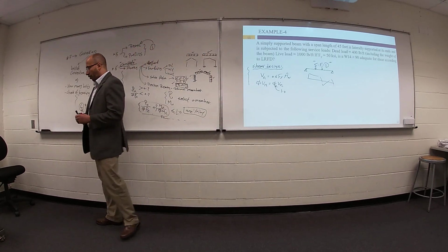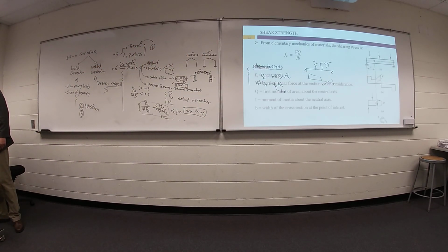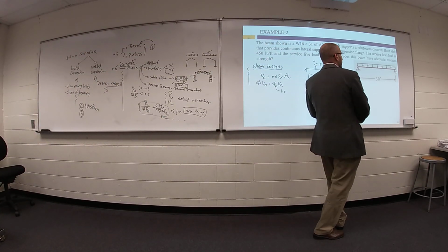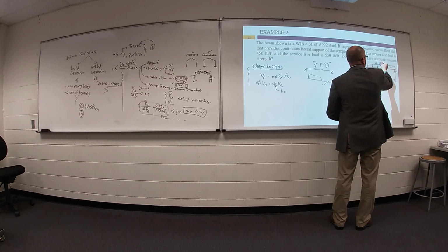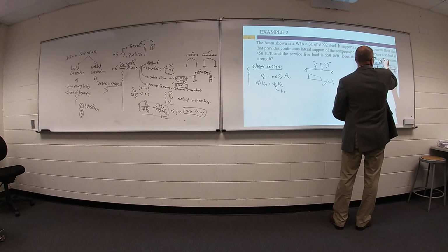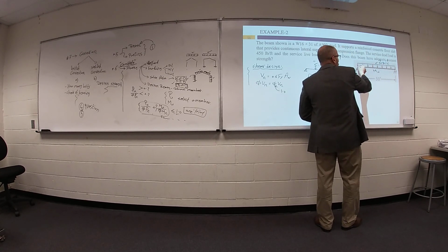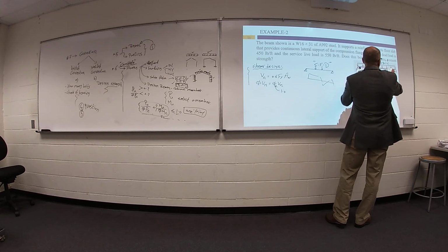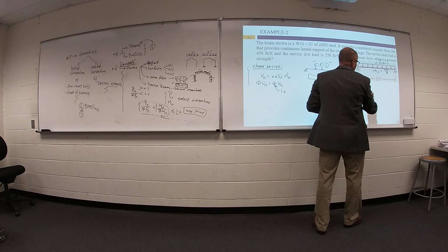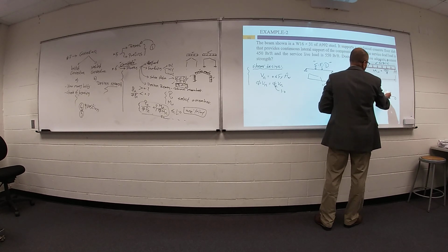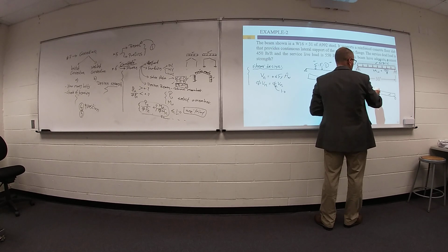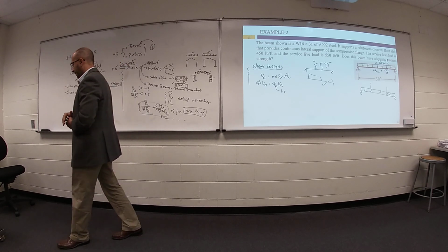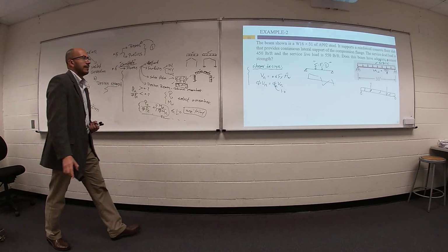Also, for the previous problems, if you have trouble determining M ultimate due to the given dead load and live load, after multiplying by 1.2 and 1.6, go ahead and draw your bending moment diagram. But for this one, it's very simple. For a simply supported beam with distributed load, your moment is WL squared over 8. But sometimes your beam is more complicated, maybe with distributed load, concentrated load, or something like this, so you need to figure it out. Anyway, your beam will be simpler.